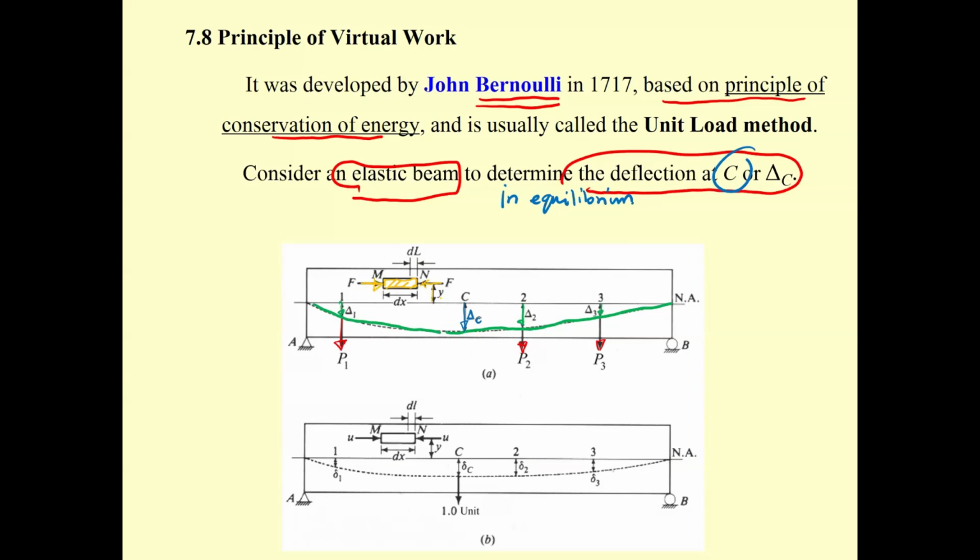Imagine for this beam during the deformation, if there is a 1 unit force applied to this beam, thinking about it again: if the force is here, the deflection is here, and linear elastic behavior occurs over here for a constant force and an assumed deflection. We have this area, and this external work is going to be P times delta.